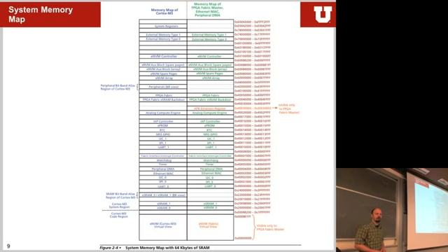Okay? Yes? You mean we have three another register for every register? Two more. But that's not always the case. That's just sometimes how they implement, in some peripherals, certain techniques. Yes. So for example, they use the status as the storage register, and then applying and changing things on that register, you use these two different registers to write into certain bits and to clear certain bits themselves. I think this is easier. This is also how it's often done, especially for things where you can get problems with writing and reading into it.